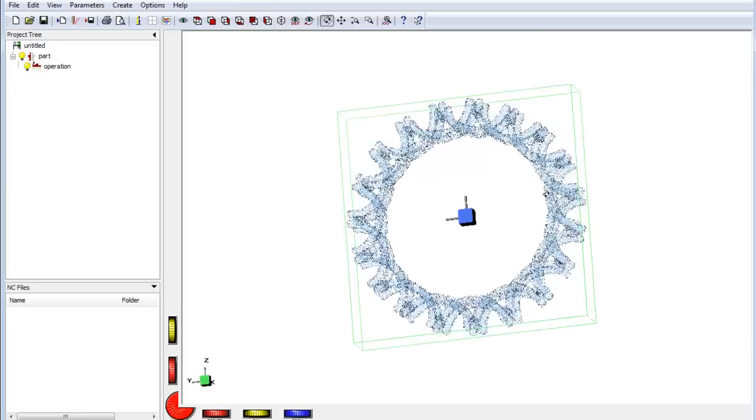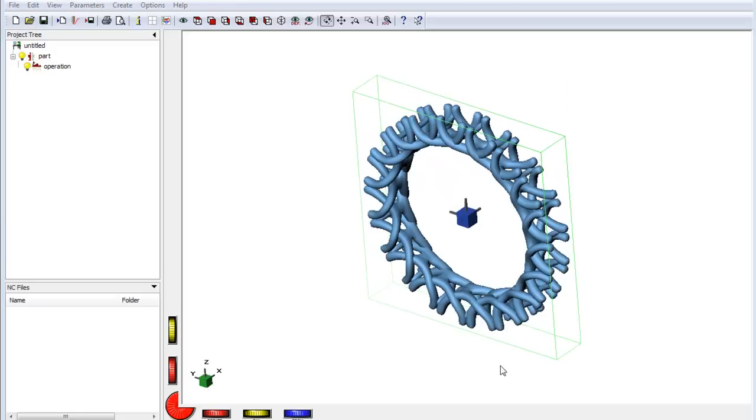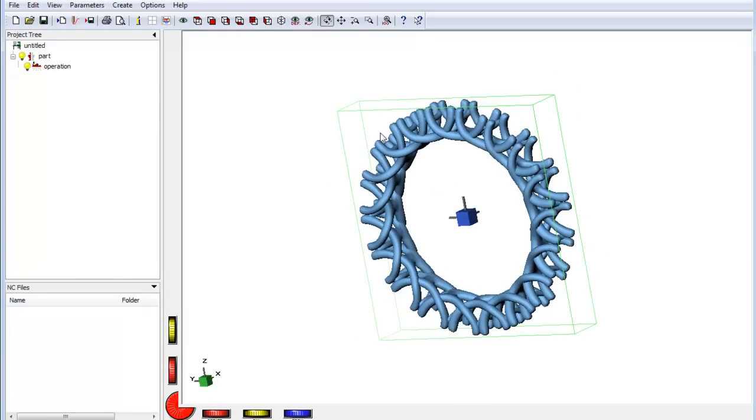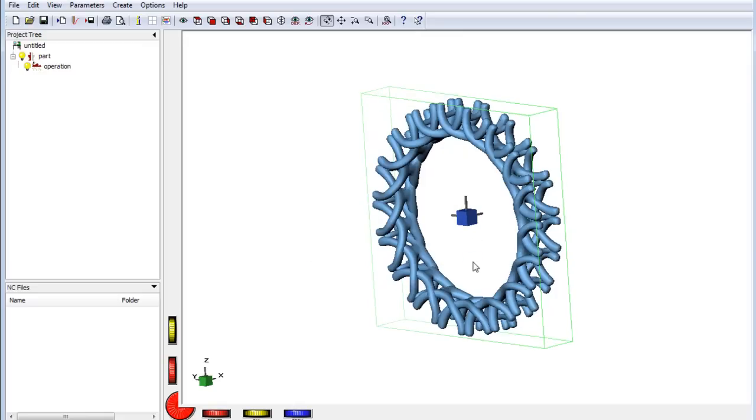So the first thing you're looking at is I've got a square block around my rotary ring, and the first thing you notice is, alright, everything is centered, but I've got a square running around my geometry. This is your first warning sign that things are not the way they're supposed to be. We're trying to cut a rotary using an index. An index is square, rotary is round.